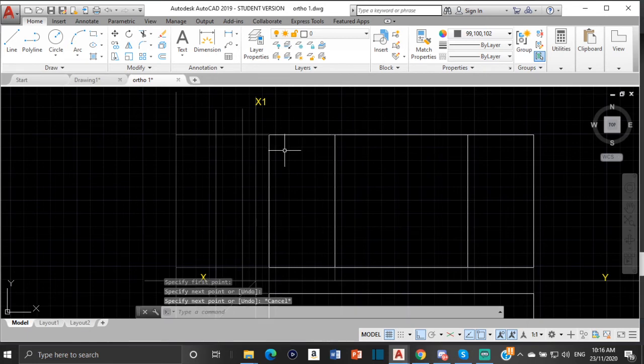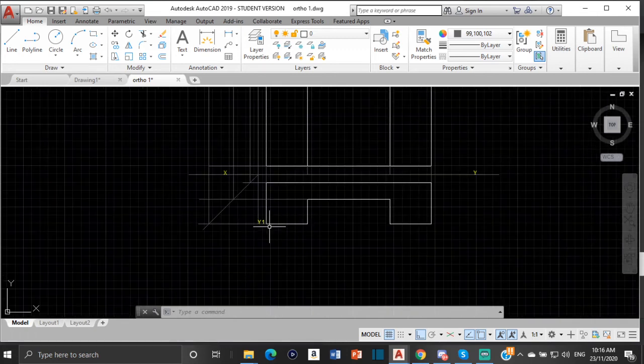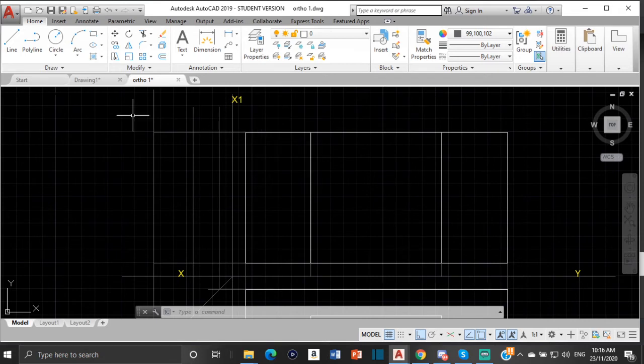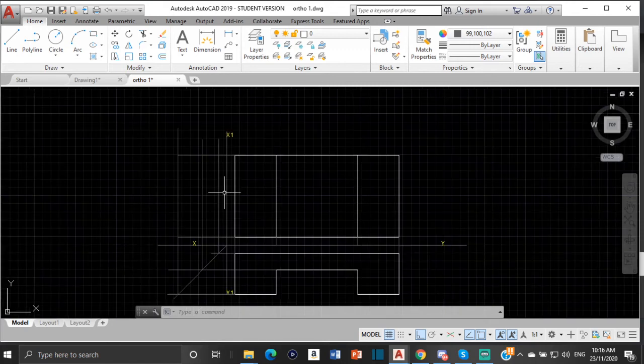All right, I might have been going a bit fast, so let me just do a quick recap. All I did was all of these edges, I would bring them across. I don't have to bring across this edge because this edge lines up with this edge, so it's the same point. So I just need to bring across this one. This edge here is the same as this, so I'll just bring across that. This edge is the same as this, just bring across that. Over here we have this edge, we bring it across, it's the same as that and that and that, because they're on the same horizontal line, so I just bring across that. Same thing at the top, bring across at this point because it's the same as that. They're all on the same horizontal line. All right, so now we have our end view, our end elevation. All we have to do is to brighten. All right, so let me just select a white line.